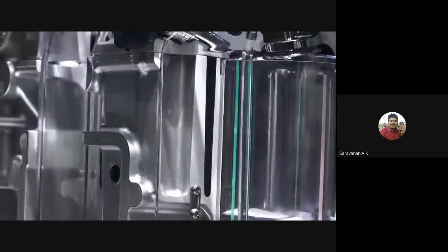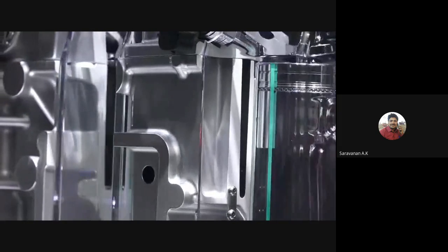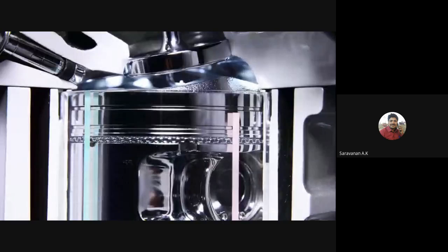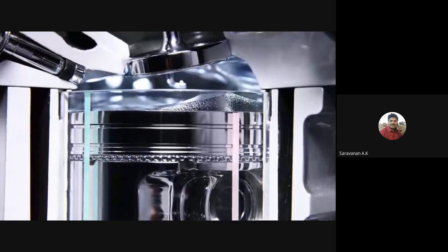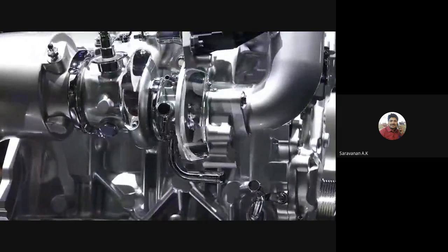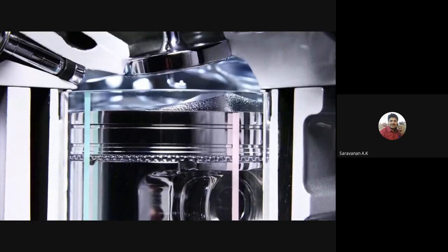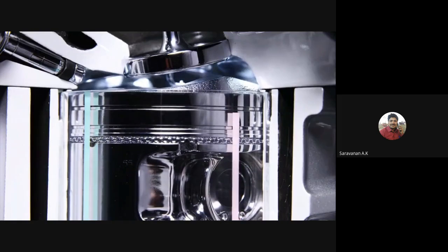So when the engine is creating its peak power of 268 horsepower or its peak torque of 287 pound-feet, it's doing so by lowering the compression ratio and maximizing boost with the turbocharger. Switching between the two extremes, from a compression ratio of 8 to 1 to 14 to 1 or vice versa, can happen in 1.2 seconds.